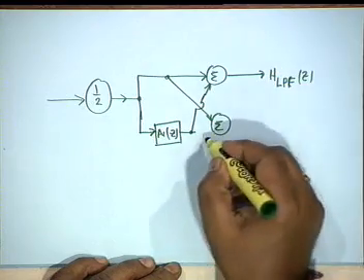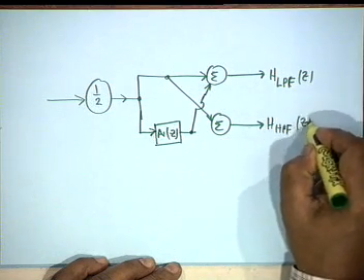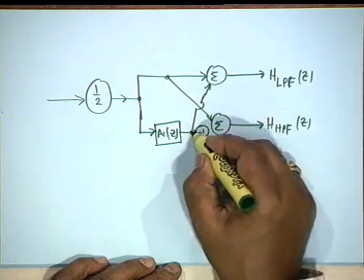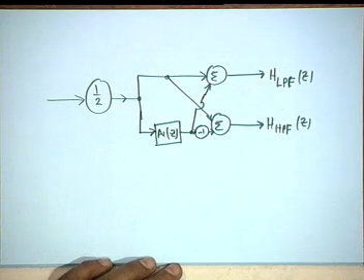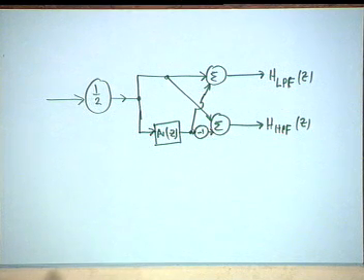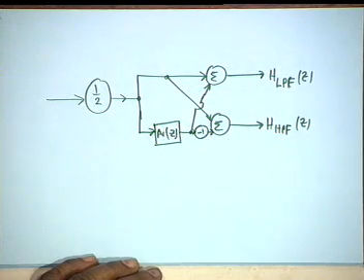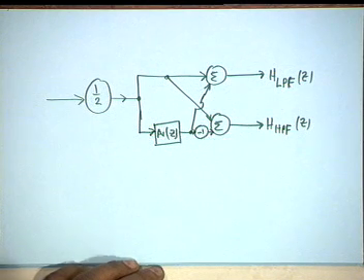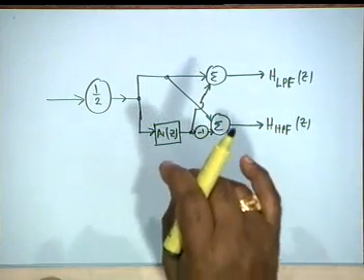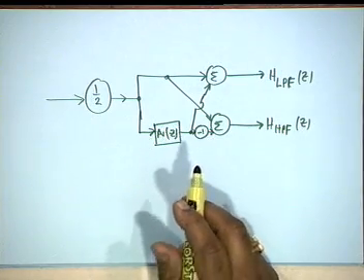and in order to create HPF you shall have to multiply by minus 1, which is not also a multiplication, it is a change in the sign bit. You see, this total thing is being realized by only a single delay and a single multiplier. If you choose to use A1(z) with a single multiplier lattice structure, which is done because it is a dedicated chip, it is programmable only in alpha, nothing else.